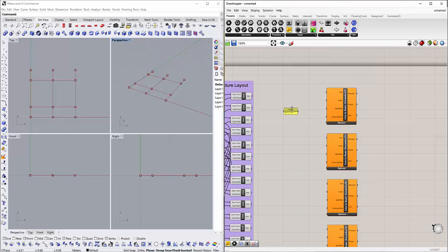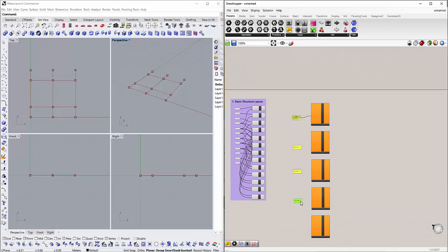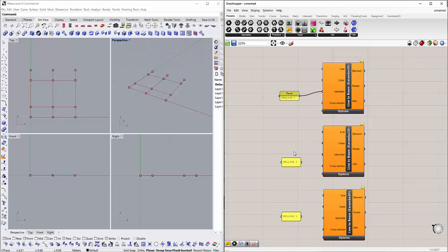So you get directly a panel of mullion 1 and you identify now this mullion 1, this line beam as this mullion 1. So now I select this panel again, copy it here, do this again, and yep, here.